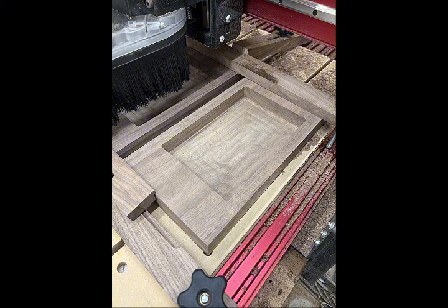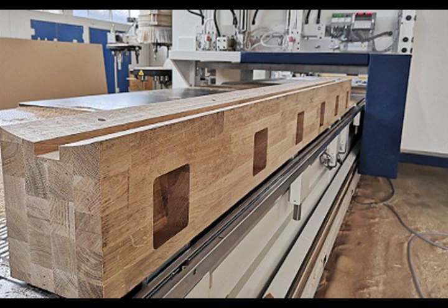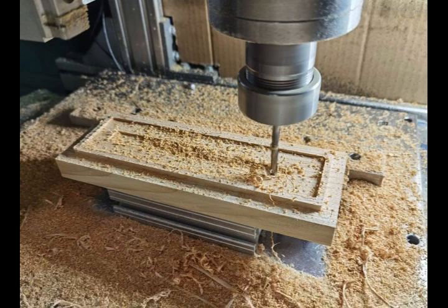Cutting depth. Cutting depth describes how much material is removed during a single machining pass. Shallow cuts generally produce excellent surface quality but increase machining time. Deep cuts improve productivity but require more spindle power, stronger machine rigidity, and carefully selected feed rates. Professional workshops always try to balance cutting depth with machining efficiency.